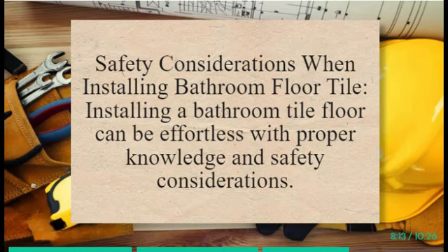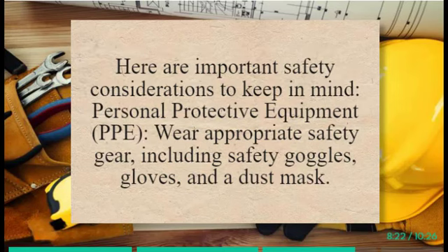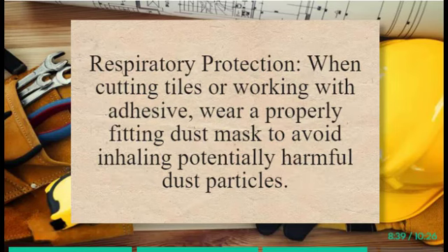Safety considerations when installing bathroom floor tile. Installing a bathroom tile floor can be effortless with proper knowledge and safety considerations. Safety is paramount when installing bathroom tile flooring. Here are important safety considerations to keep in mind: personal protective equipment, PPE. Wear appropriate safety gear, including safety goggles, gloves, and a dust mask. These protect you from tile shards, dust, and chemical irritants.